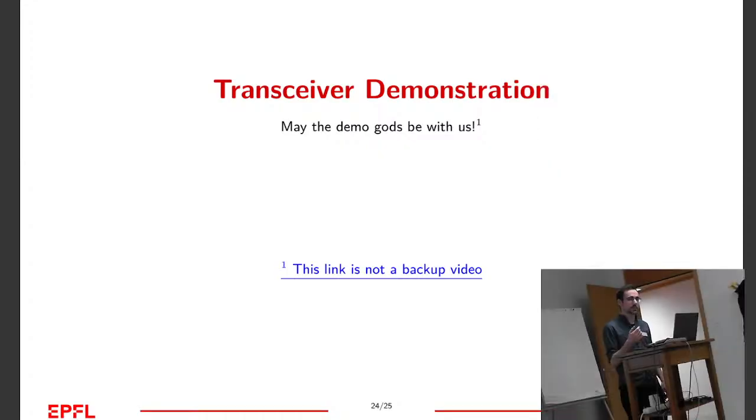To transmit on the ISM bands, you can do it for free, but there are some restrictions in place. You cannot transmit more than 1% of the time. So if you transmit for 1 second, you need to wait for 100 seconds. So if you transmit in one channel for too long, then for the next transmission you switch to another channel. That's 1% per channel. You randomly choose which channel to transmit on? Usually, or the simple way is to just alternate. So the receiver has to listen on all of them.